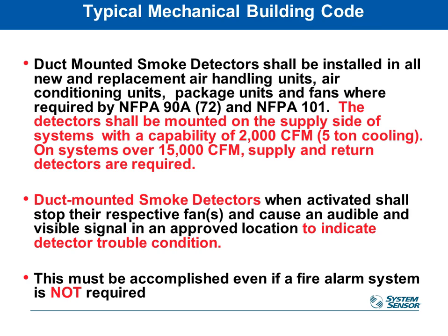Additionally, what we often do, although it's not required by code generally, is shut the outside and exhaust dampers. There's no reason to continue to bring air into the building to feed flames, and also we don't want the equipment to freeze or anything like that. And then if it is hydronic heating and cooling, we open up those valves. We open up the hot water valve, we open up the chill water valve to prevent those lines from freezing with any outside air that's leaking in.